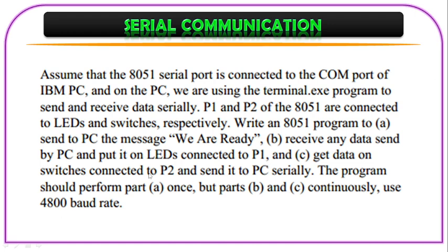And then get the data from port 2 and send it to the PC serially. So get data from the PC, put it on P1, and then get data from the switches on P2 and send it to the PC serially. So port 1 is an output port, port 2 is an input port.